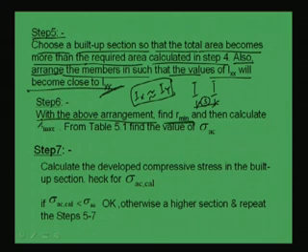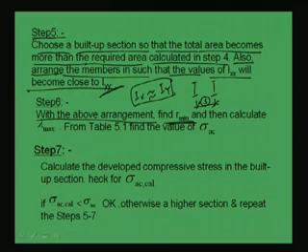find R minimum. R minimum is the minimum radius of gyration. Now, to get maximum efficiency, that means to get maximum strength of the member, we will get Rx equal to Ry. However, if it is not possible, then we have to find out what is the R minimum, okay, and then calculate lambda max. R minimum means we will get lambda max, okay.